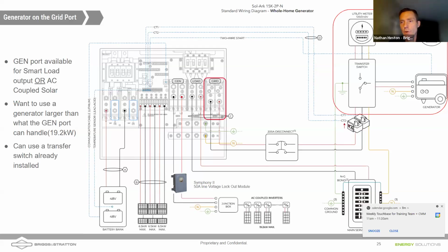The limitation for backfeeding to the grid would be 40 amps on a 200 amp panel unless you have a specifically designed solar main load center, right? Because of the 120% rule, you can only feed a 200 amp panel at 40 amps, unless you have bus bars that are oversized in there. Or you derate the main.